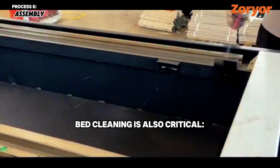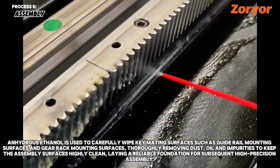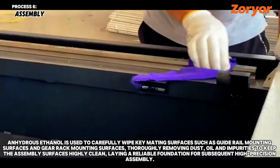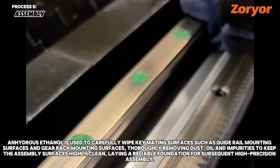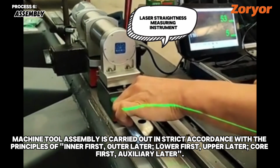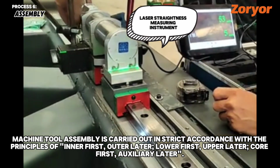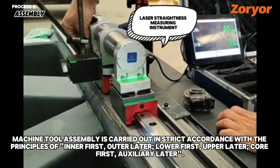Bed cleaning is also critical, and hydrous ethanol is used to carefully wipe key mating surfaces such as guide rail mounting surfaces and gear rack mounting surfaces, thoroughly removing dust, oil, and impurities to keep the assembly surfaces highly clean, laying a reliable foundation for subsequent high-precision assembly. Machine tool assembly is carried out in strict accordance with the principles of inner first, outer later, lower first, upper later, core first, auxiliary later.